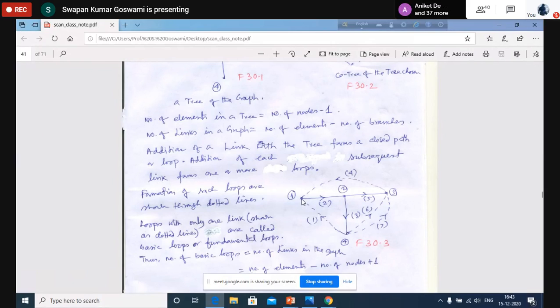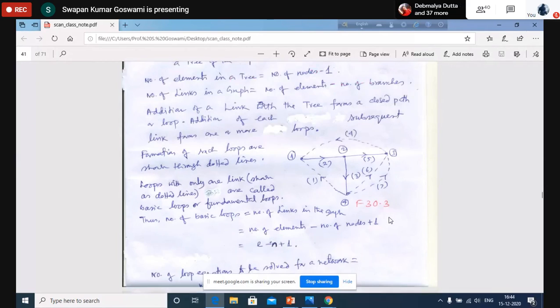So in this product A times IE, the first row is minus I1 plus I2 minus I4 equal to 0. Similarly, in the second row we got minus I2 plus I3 plus I5, or I5 plus I3 minus I2, that is also equal to 0. Similarly, at node 3, there are 4 elements. It should be I4 minus I5 minus I6 minus I7.